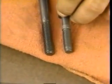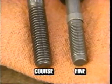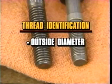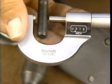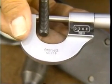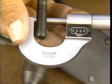The threads on the bolt can either be coarse or fine. Coarse threads are farther apart than fine threads. Threads are identified by measuring the outside diameter and thread pitch. The outside diameter is measured using a micrometer across the high points of the threads. The actual measurement is usually less than the given thread size. How much less depends on the tolerance allowed in manufacturing.